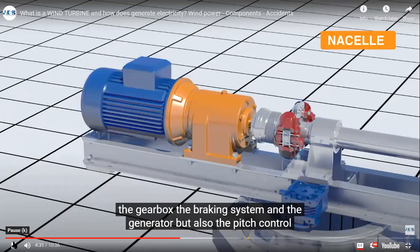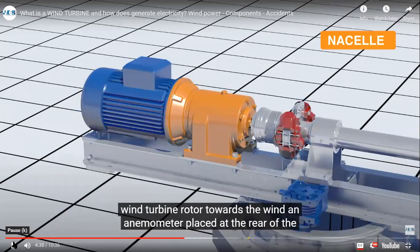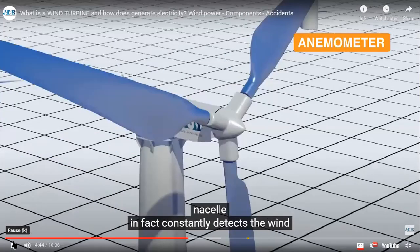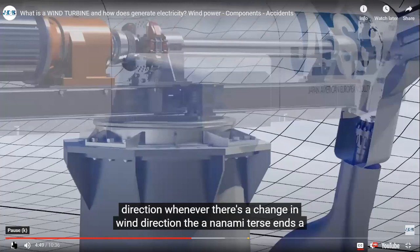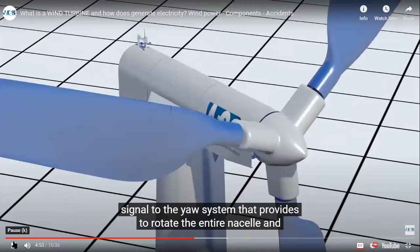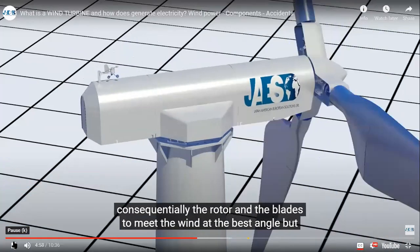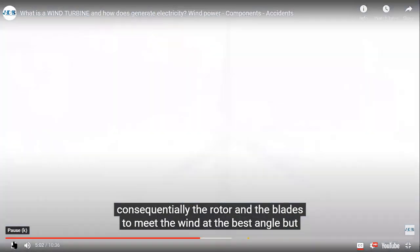But also the pitch control system and the yaw system, which is responsible for the orientation of the wind turbine rotor towards the wind. An anemometer placed at the rear of the nacelle, in fact, constantly detects the wind direction. Whenever there's a change in wind direction, the anemometer sends a signal to the yaw system that provides to rotate the entire nacelle and consequentially the rotor and the blades to meet the wind at the best angle.